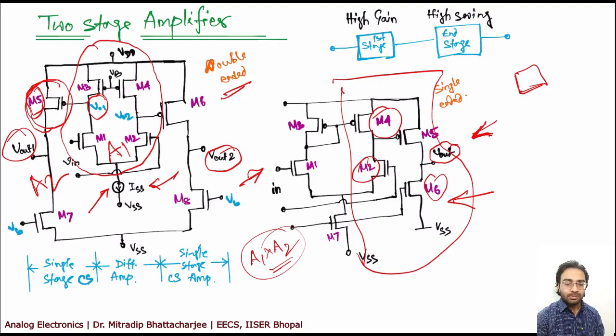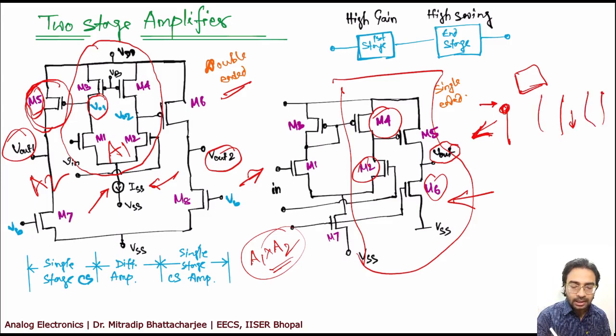So what generally people do is, I already have shown you one current mirror. They use current mirrors to replicate the source, because in current mirrors, if you remember, you set the bias on this side, and you'll get a similar current on the output side. Now if you put them in parallel and vary the W by L ratio, you will get different current sources at the same time.